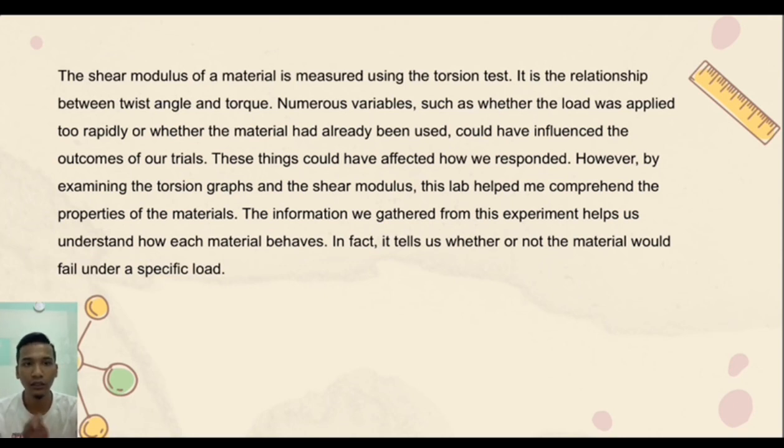However, by examining the torsion graphs and the shear modulus, this lab helped me comprehend the properties of the materials. The information we gathered from this assessment helped us understand how each material behaves. In fact, it tells us whether or not the material would fail under a specific load. That's all for me. Thank you.